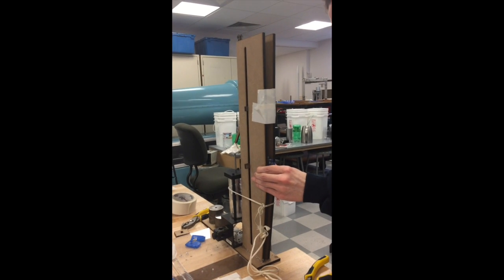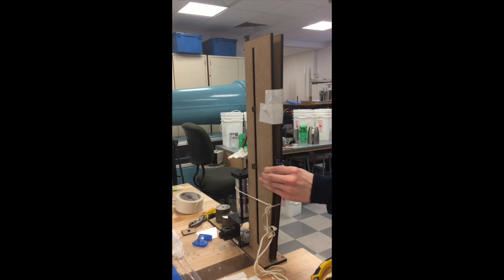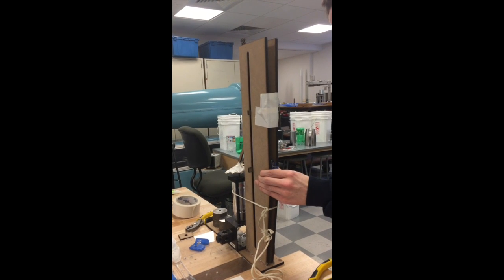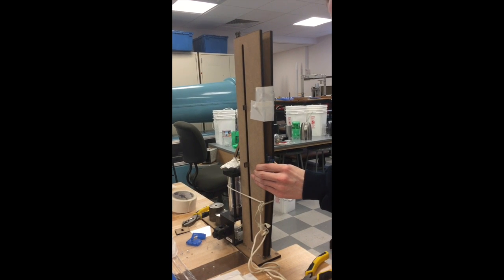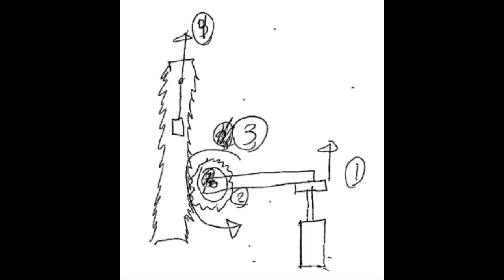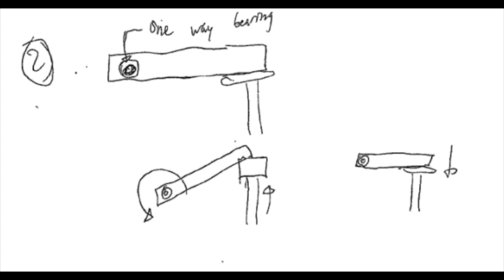For the design of our heat engine, the goal was to work off of a specific group's design and try to make improvements upon it to increase the total energy stored. We planned on using a one-way bearing along with a rack and pinion mechanism to lift to a higher height. By using the expansion work of the piston, this would push a lever, which would then push our rack upwards. The one-way bearing would prevent the rack from falling when the piston would lower from the metal canister being cooled.